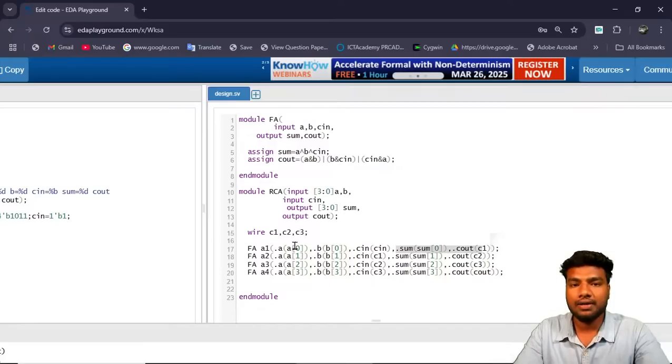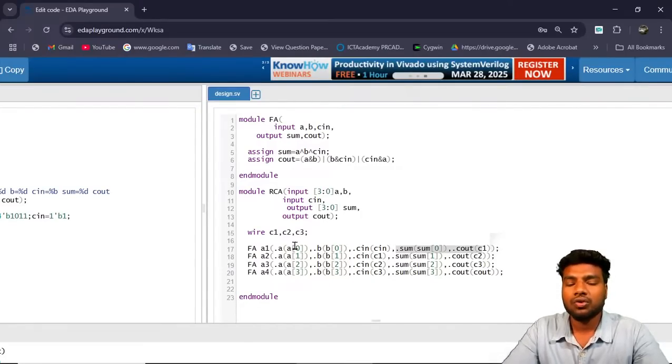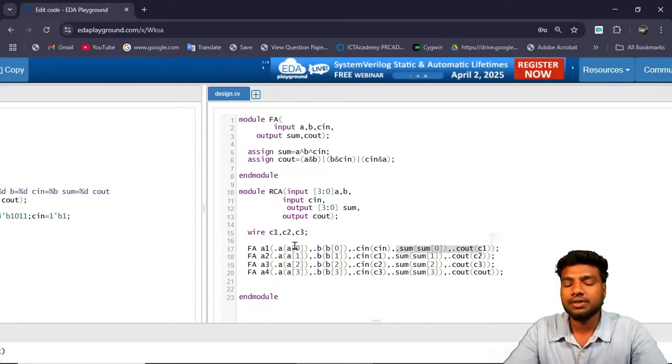If you want to add delay, you just need a counter. Counter is the basic thing to add the delay. And if you want to decrease the frequency, say your input clock is 50 megahertz and you have to decrease it to 25 megahertz, you have to use a counter. We'll see counter operation in the upcoming sessions, I think tomorrow.